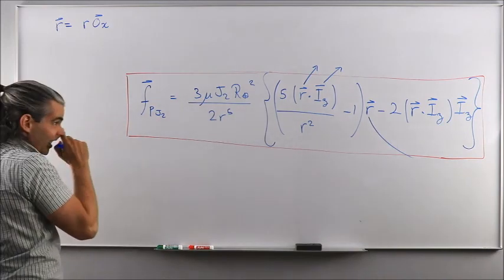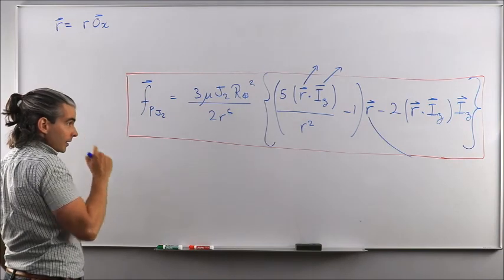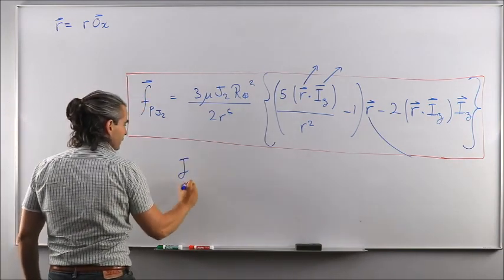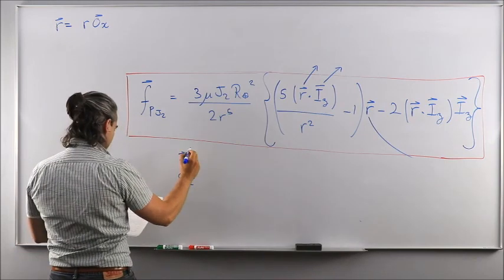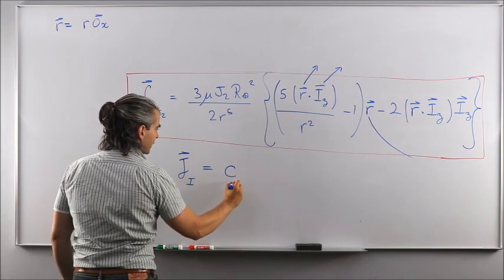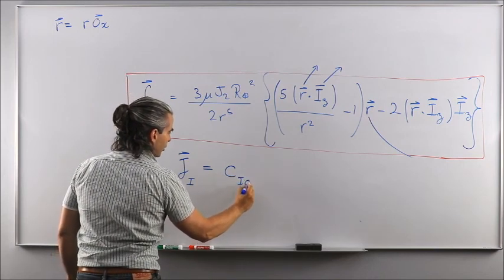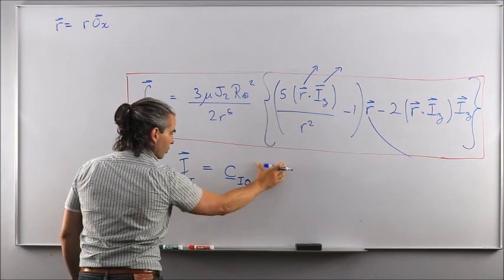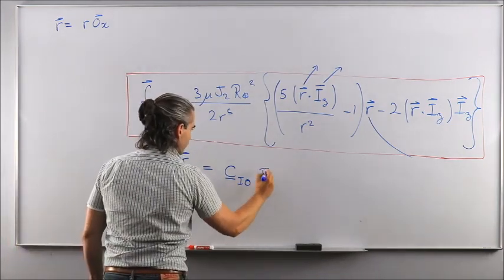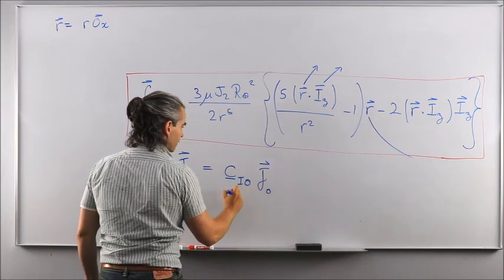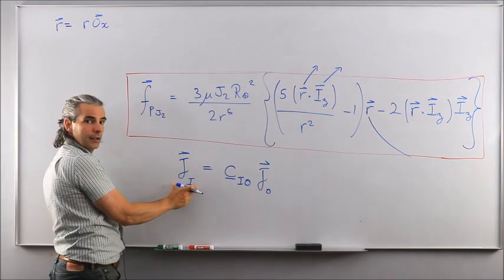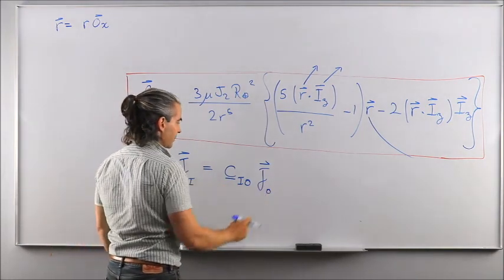To do IZ in the orbital reference frame, we have to use the vectrix related to the ECI reference frame, equal to the rotation matrix CIO, taking us from O all the way to I. Remember, this is the first use of a rotation matrix, to relate the orientation of, in that case, ECI with respect to the orbital reference frame.